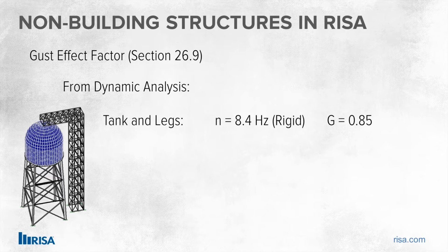For the tank and its legs, I found one fundamental frequency, which was at 8.4 hertz. Now, since that's greater than 1 hertz, we would consider that rigid, so the code allows us to take a simple gust effect factor of 0.85.